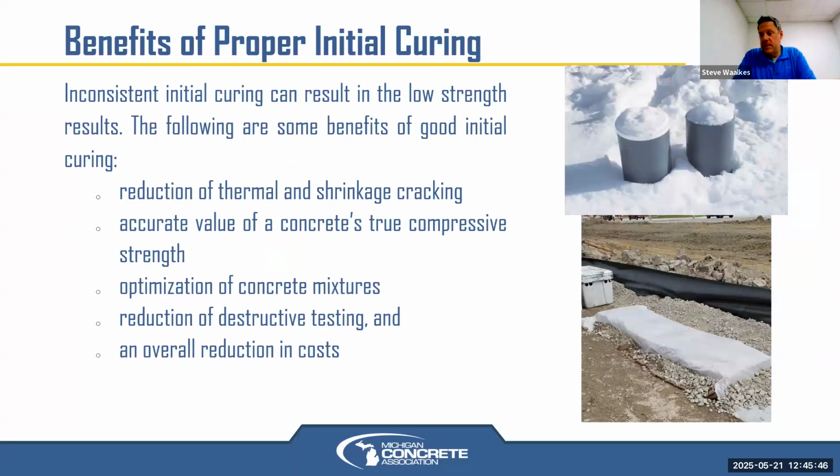You don't want them to freeze. Obviously, you want to protect them. They can't be below 60. Because if the concrete is allowed to freeze inside those cylinders prior to achieving a significant amount of strength, that will cause damage, and you'll get low breaks, and then you'll think, oh, they gave us a bad mix. Our concrete is bad. It's going to fall down. It's going to have cracks. But was it just the cylinder, or was it the actual in-place concrete that is the issue?